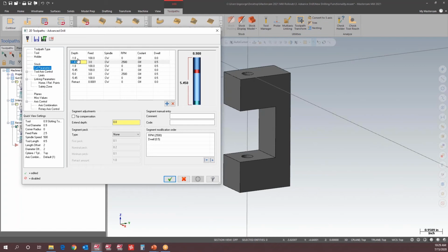And then we're going to rapid back down, turn the spindle off, then rapid through again, turn the spindle back on, and cut upwards again, rapid out, turn the spindle off. You know, I got dwells in here too, right? The dwells are going to make sure when that spindle turns off, that tool's got enough time to retract back in. Once that tool retracts back in, I can just wrap it all the way out that pilot hole.